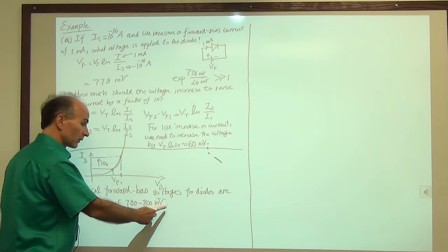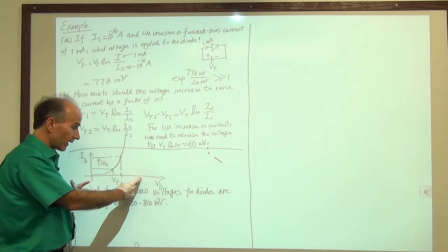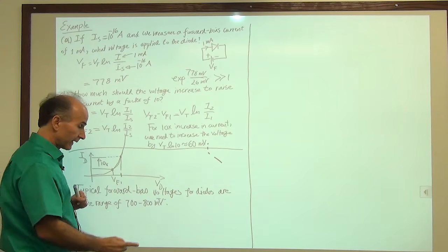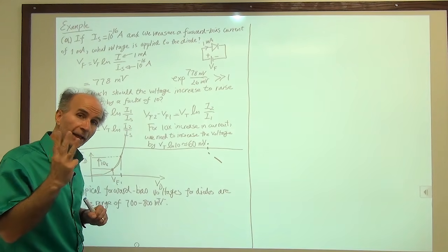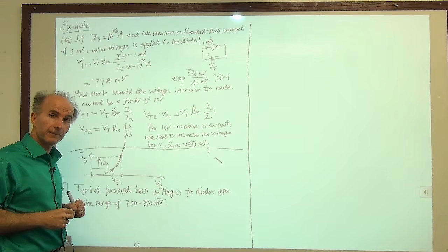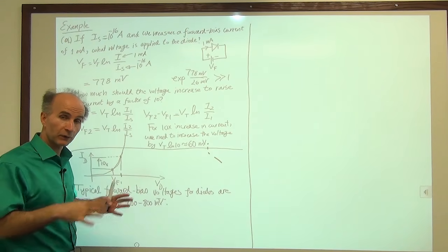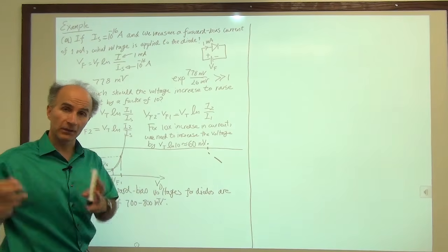So if you have a diode that has 1000 millivolts across it, then that diode carries a current about 3 orders of magnitude larger than the numbers that we are dealing with here, right? So instead of 1 to 10 milliamps, we're talking 1 ampere to 10 amperes.